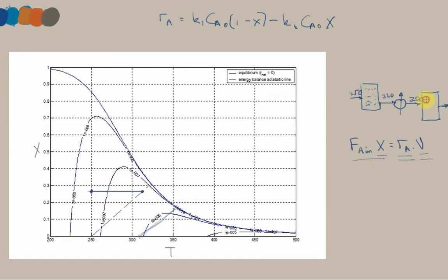And then if we also have another catalytic reactor here, then that can react further. And we'll prove just now that that will increase on a line that's parallel to the first one. So you see, that's how we can achieve higher conversions. That's how we can access these other regions on our isorate line graph. And of course, there's nothing to stop us introducing yet another cooler here. So we have a cooler here, and then we could introduce another reactor over here. And so we can indeed step up along this line.